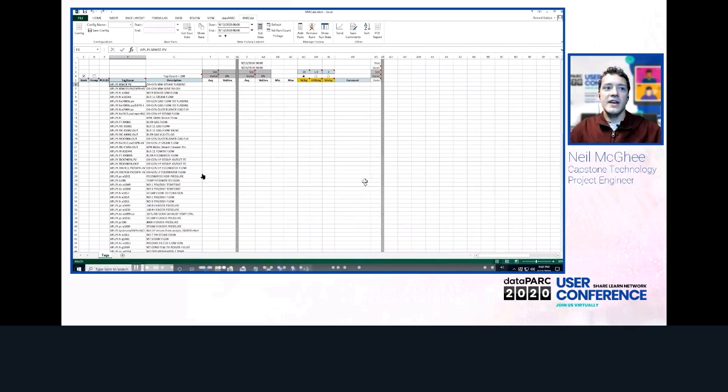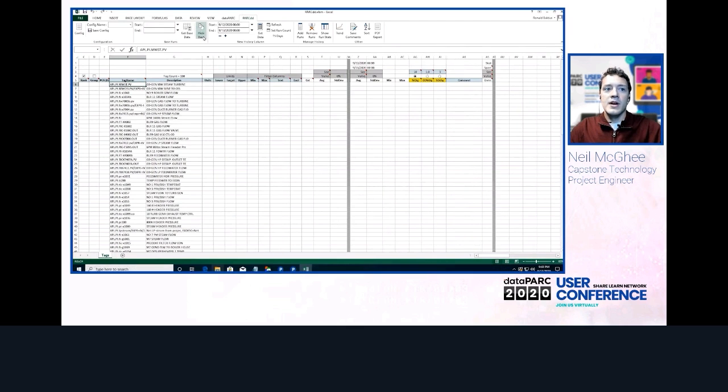After we have added our tags, we have several other columns that we can configure. First, we need to show hidden columns. I'll step back through the other columns in a minute, but for now we're going to focus on the filter columns. This is where we manually configure tags to filter out process downtime for analysis.